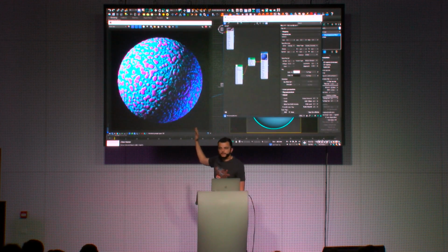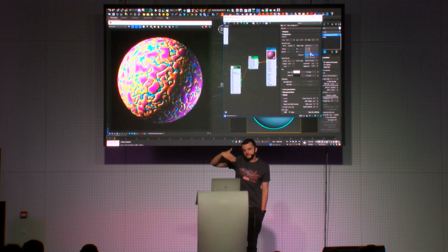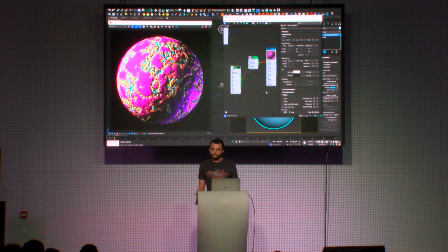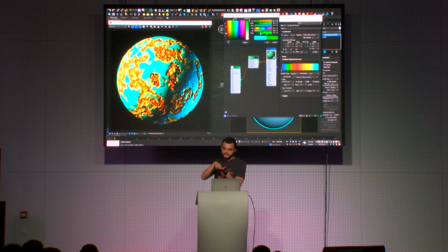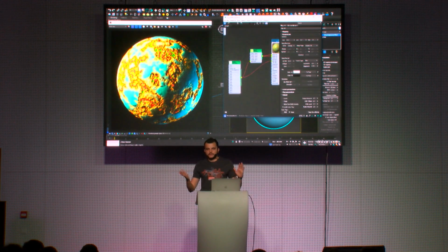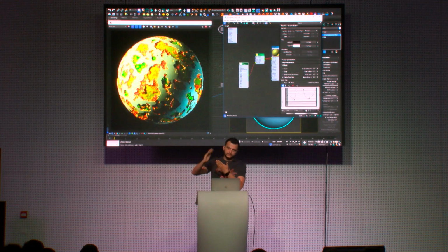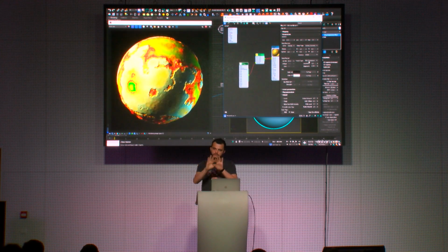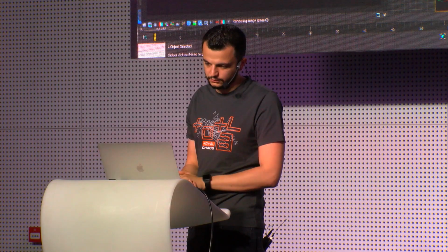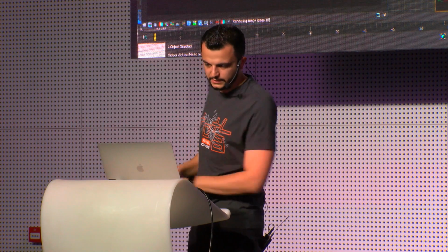They can even use scene-specific information, like the angle at which the ray falls on the surface. Then you can make an effect so that on the edges or on round shapes, some things appear different than when the ray hits it perpendicularly, for example. There's a bunch of stuff that people can do. And they can go as deep as the user wants. A procedural texture can be input for another procedural texture, and this can continue for a while.